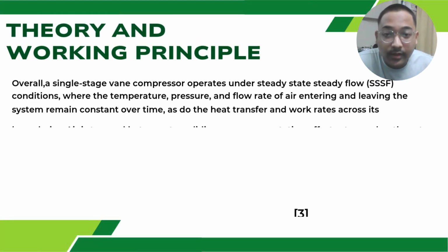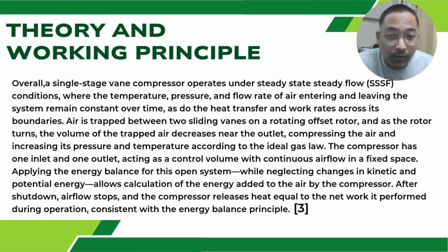Overall, a single-stage vane compressor operates under steady flow (SSSF) condition where the temperature, pressure, and flow rate of air entering and leaving the system remain constant over time, as do the heat transfer and work rates across its boundary. Air is trapped between two sliding vanes on a rotating offset rotor, and as the rotor turns, the volume of the trapped air decreases near the outlet, compressing the air and increasing its pressure and temperature according to the ideal gas law.